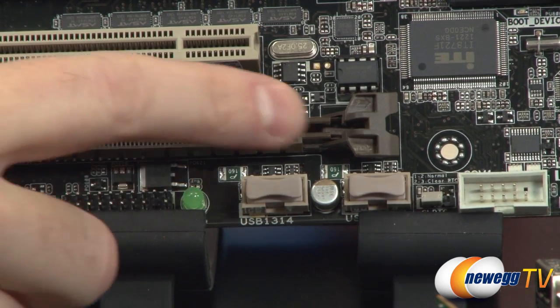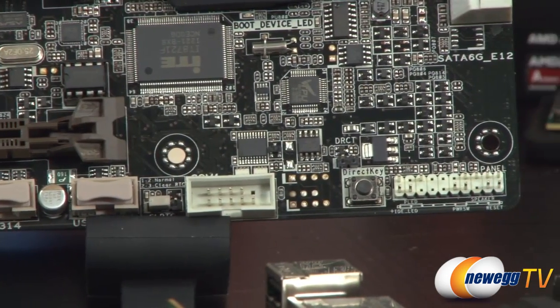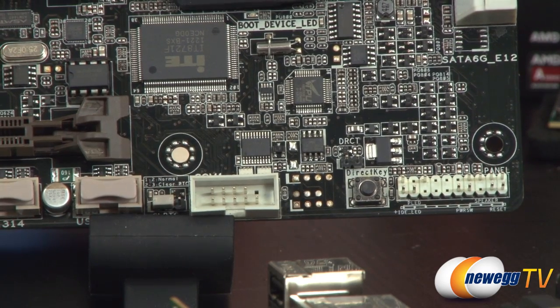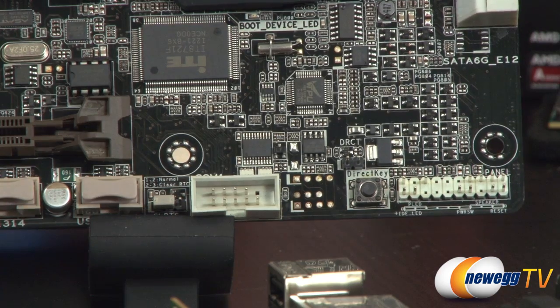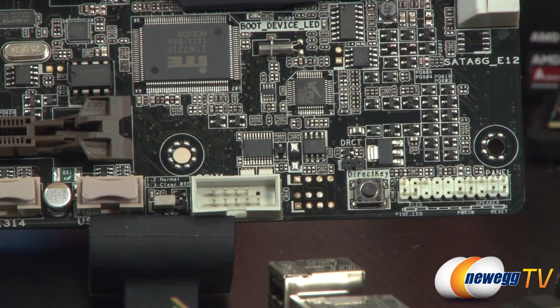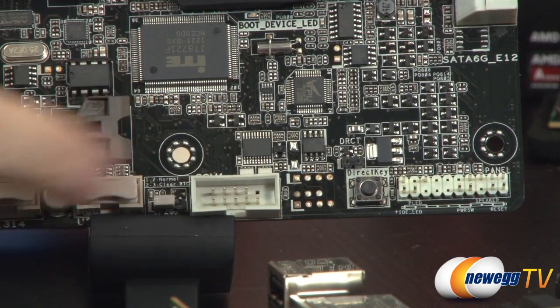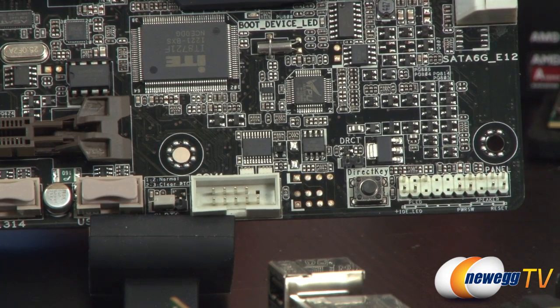Asus also, over on the right side here, has a little button called Direct Key, which I've been growing more and more fond of, because some of the motherboards now with the current generation processors, and if you're using Windows 8 for example, can boot so fast that it's difficult to get into the BIOS. You usually have to push a button or something. And that Direct Key, you push that button, reboot the system, and it will automatically go into the BIOS. You don't have to spam the delete button or anything like that.